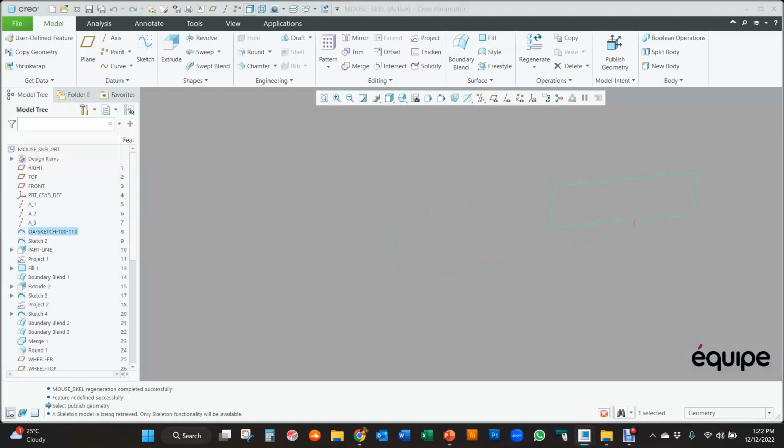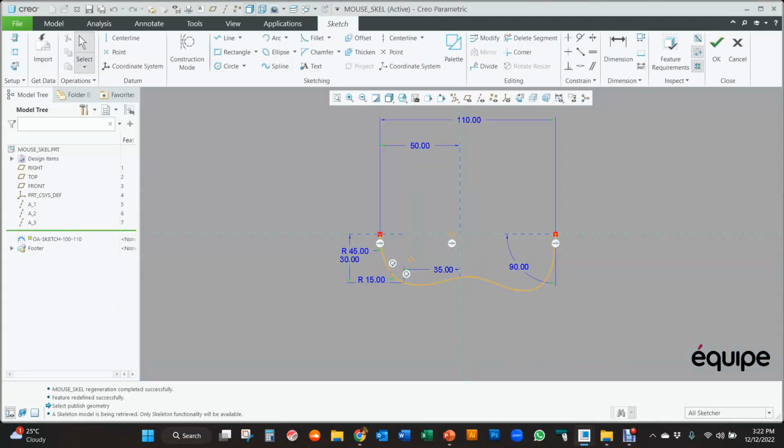And so the advantage of this sort of reference control, the entire length of every component and the product as a whole is driven and constrained by this one sketch, and then all the features that built off this sketch will update. So this is currently 110.